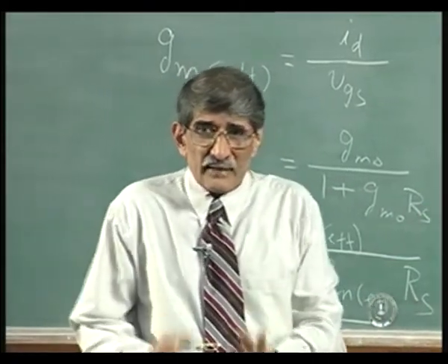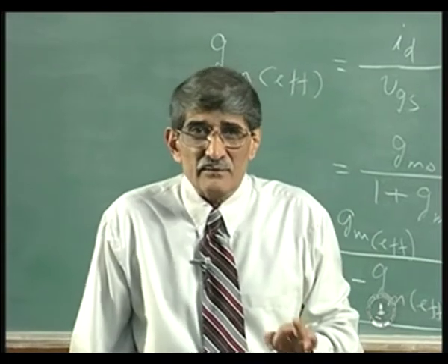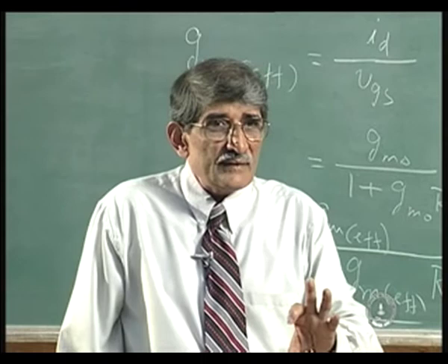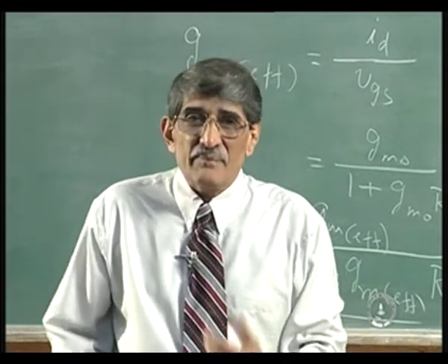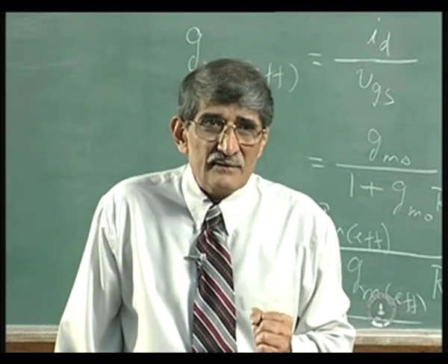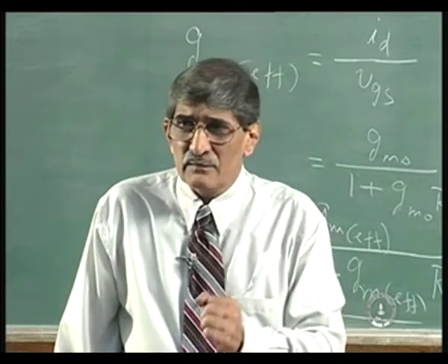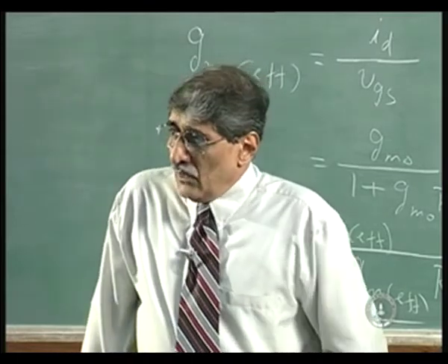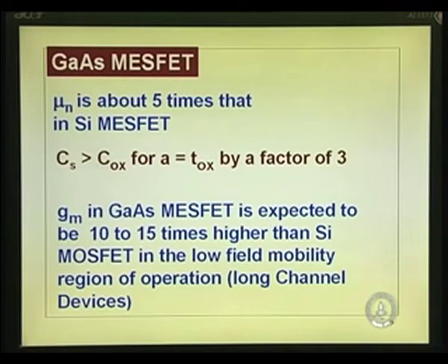We are not worried about current so much, we are worried about transconductance, because that gives how much change in current for a change in voltage, which gives the driving capability of the device. So GM is the most important thing, whether you talk of bipolar, MOS, MESFET, whatever it is, the comparison should be that. So in a long channel device there is no problem.